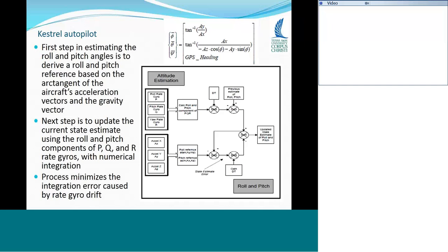All right. Well, it uses a Kalman filter, but this time the prediction and correction are a little bit different because now we're talking about attitude at the moment. We're talking about roll and pitch angles. So GPS doesn't come into it. GPS basically only gives you the location of the center of mass of the airplane, more or less. So GPS is not going to tell you if you're rolled. Okay, it's just going to tell you where you are. Okay. So there's a predictor corrector step here that's used, and the predictor step is basically using gravity.